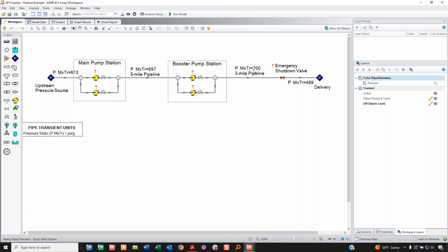And I like to emphasize that all of our software, or this Impulse, is nuclear verified. So we go through the rigorous testing to make sure our calculations are legitimate. You can use this to say, this is how I'm deciding to meet code, right? The calculations are legitimate as long as you know what your design pressure is and the max transient overpressure. The software is a good CYA move, if you might call it that.